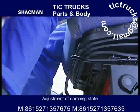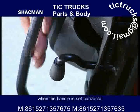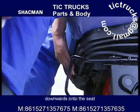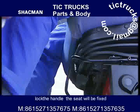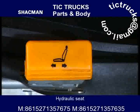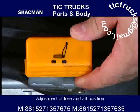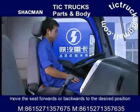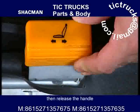Adjustment of damping state. The seat has air suspension function when the handle is set horizontal. Turn the handle clockwise to apply appropriate force downwards onto the seat. Lock the handle, the seat will be fixed. Hydraulic seat. Adjustment of fore and aft position. Pull the handle upwards. Move the seat forwards or backwards to the desired position. Then release the handle.